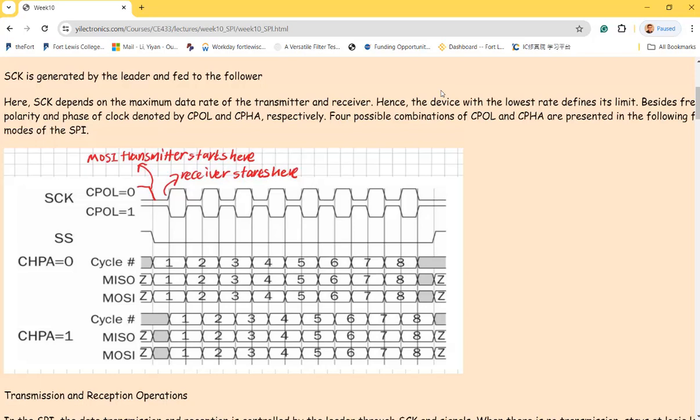It's just one clock cycle. Every clock cycle has one rising edge and one falling edge. So I have to put the data onto the line first. Then it's ready, then the receiver will take it in, right? So that's why it has to be different edges.